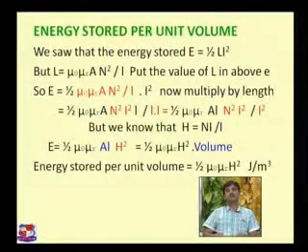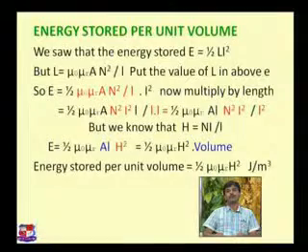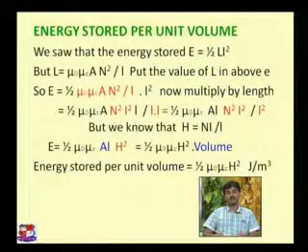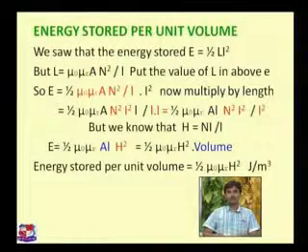Put the value of L in above equation. That is the equation from second definition of self-inductance that we have learned in last lecture. So E is equal to 1/2 mu 0 mu r A n square upon l into I square.